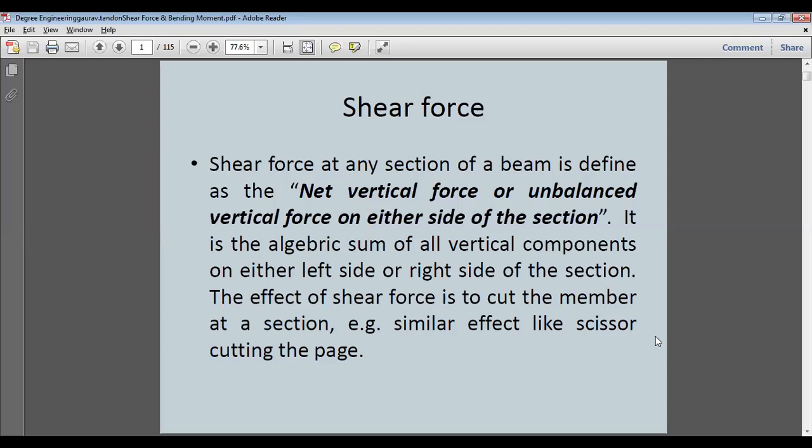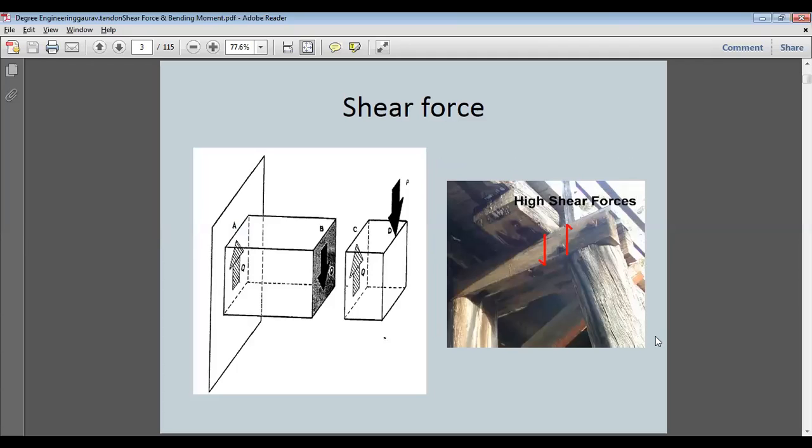As we have discussed earlier, again I am going to give a quick overview of shear force and bending moment diagrams. So I told that shear force is a force that basically acts in two opposite directions on the surface of the object, so that it tries to tear the part or component. So shear force is a force that basically tries to tear the part, to tear the beam or wherever it is being loaded.